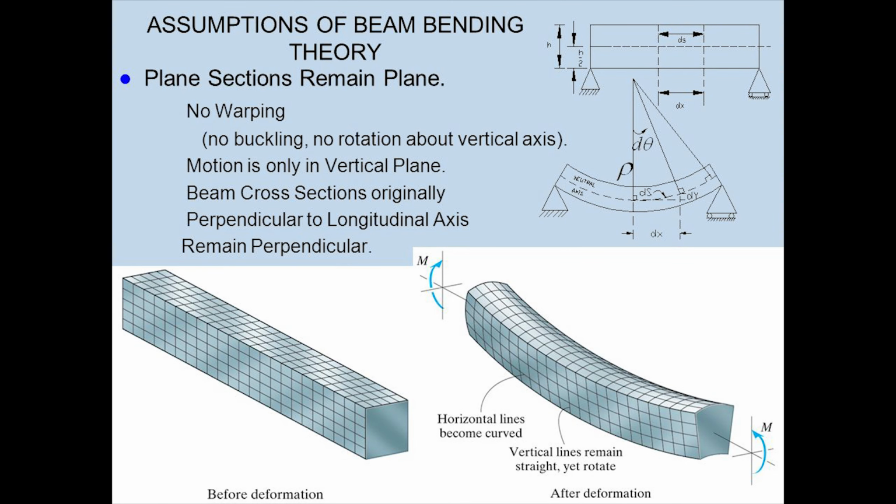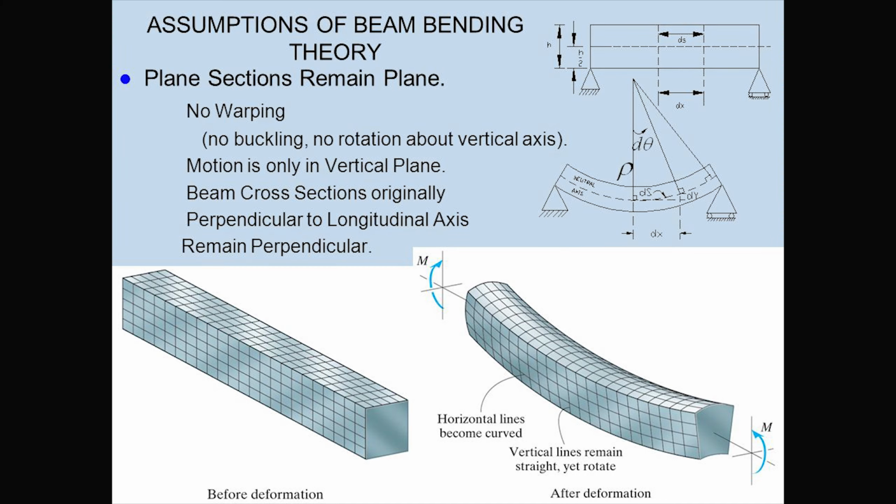For a pre-stressed concrete structure or structural steel that requires stress under the serviceability limit state or ultimate limit state, the stresses could also be obtained from line or shell elements using the so-called plane sections remain plane assumption. As explained earlier, line and shell elements are the practical finite element model for the structural design of a building.